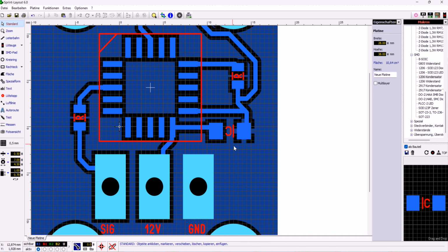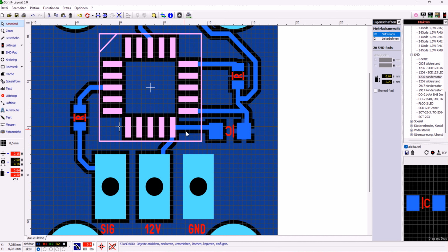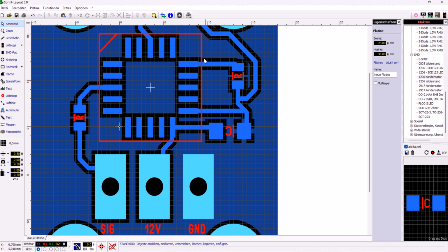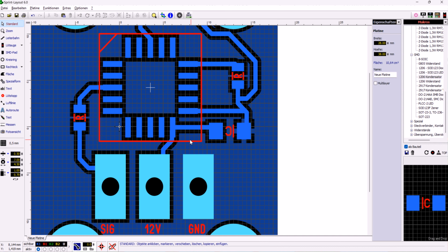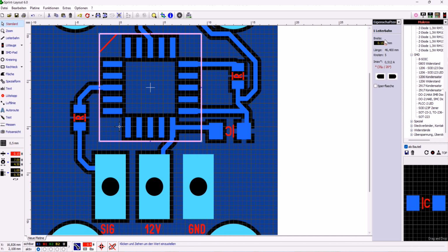That way you can also alter some other items. Like this, of course, is a macro too, and if you would want this outer line wider, you don't have to disassemble the macro. You also could hold the Alt key, in this case one click on it, and then you could do something like that and play around. Once you click away somewhere on your PCB, it's still one macro. You just edited that one part of the macro.